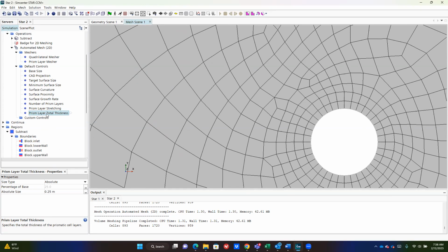So let's just change a few parameters. First one, let's look at a prism layer. You probably don't know what it is really all that much yet, so I'm going to just focus on that. I'm going to make this 31 cells in a prism layer. So it's going to make a thickness of about 1/4 of a diameter, and it's going to put 31 cells in between.